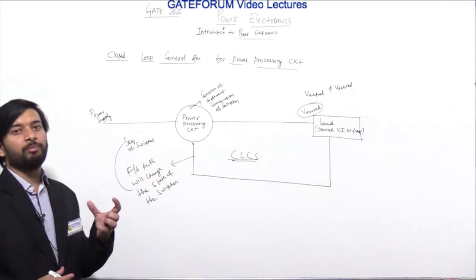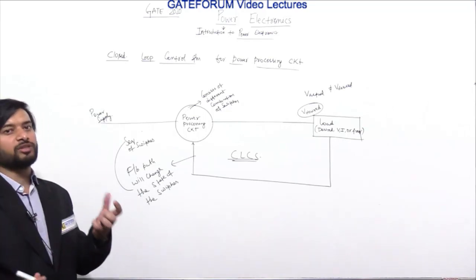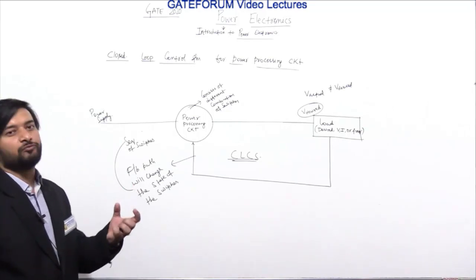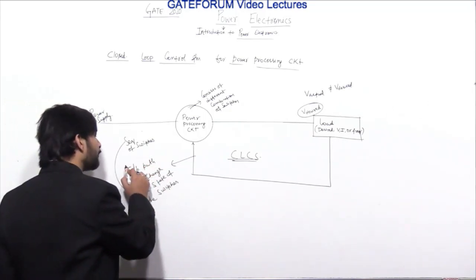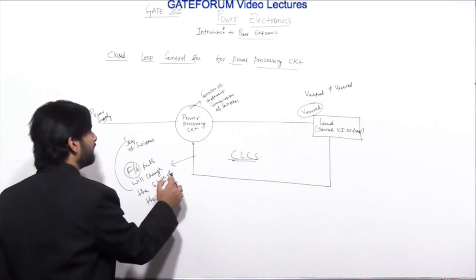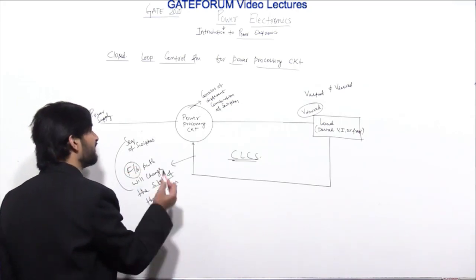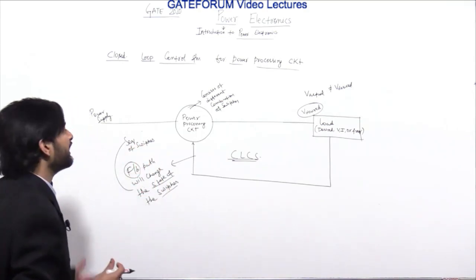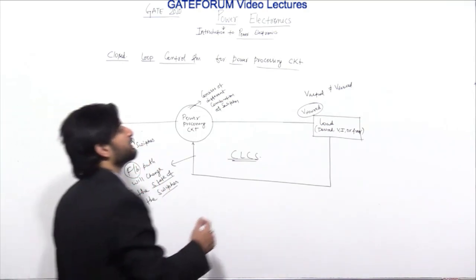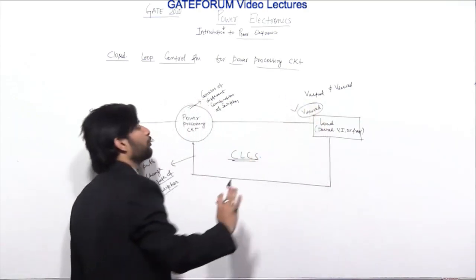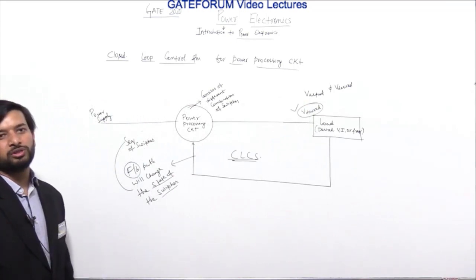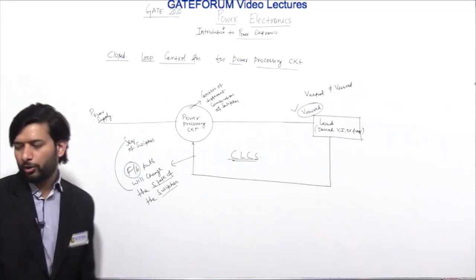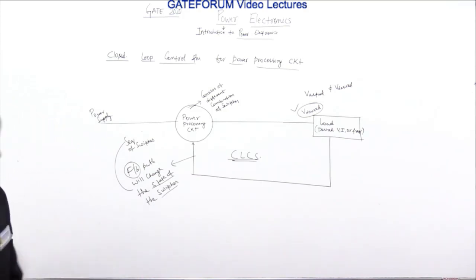Because switches are what connect the source and load. Switches are only the means for connecting the source to the load. So if a proper feedback path is provided, it will turn the state of the switches in such a way that the sequence of the switches connects the source and load such that you will be getting V desired, and the closed loop control operation will be stopped. This is how a closed loop control system is incorporated in a power electronic circuit.